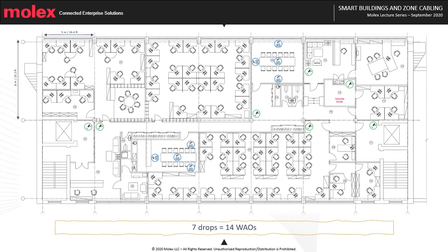Now, we shall add all our equipment outlets to connect our IP cameras. Please also note that we could also have used MPTL connectors for these IP cameras, which would provide additional benefits. Because indeed, as IoT and intelligent buildings continue to converge, more devices are being installed without the traditional RJ45 work area outlet, such as in locations above the ceiling or on the wall. Some good examples of this include wireless access points, PoE LED lighting systems, AV displays, and IP cameras. Nowadays, more of these devices are designed with built-in RJ45 ports.